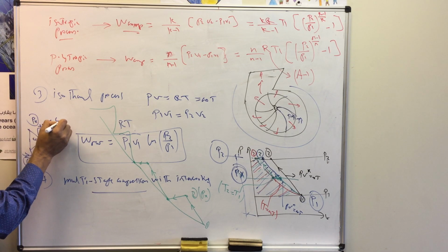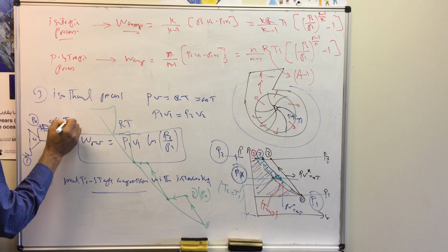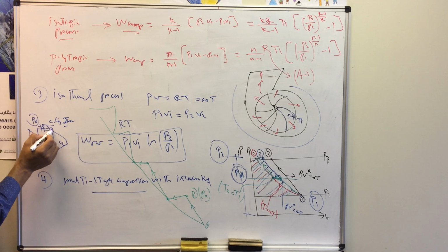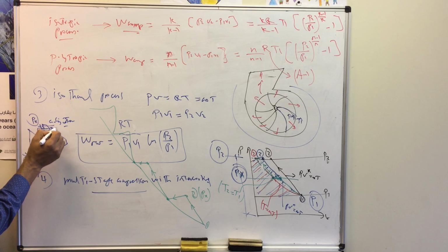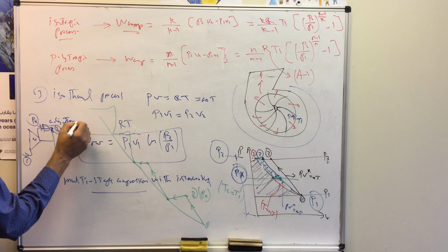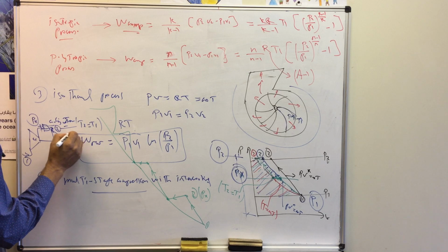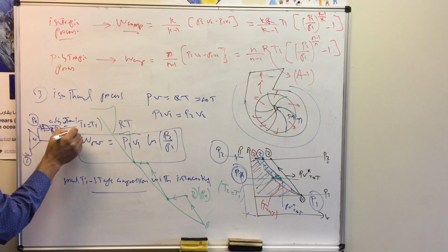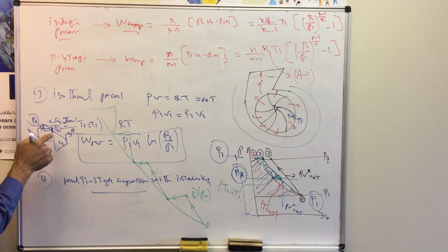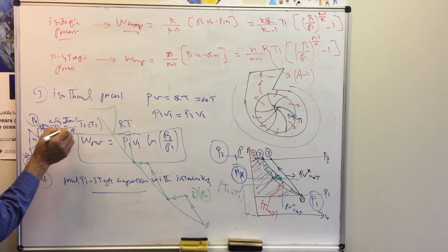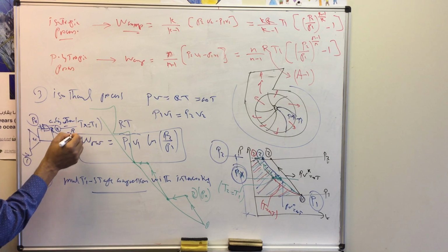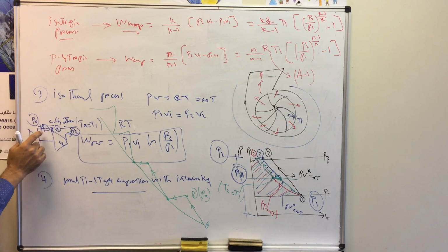Let's say we have cooling water or something. So then we can cool down this air before it is introduced to the second compressor. Let's say this is point 2. In this case, the temperature T2 is getting back to the same initial temperature T1. Then we can do the compression process from pressure Px up to the final pressure of the system. Let's say this is point Px, so Tx is the same as T1. Then we can raise the pressure from Px up to P2 in the second compressor.